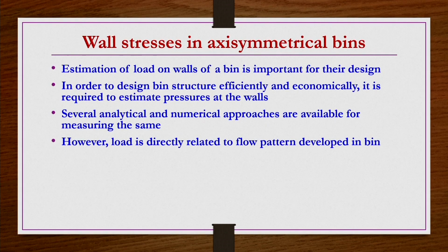However, load is directly proportional to what kind of flow pattern is there inside the silo when the discharge is started, or when the feeder is open to take the material out. So, what kind of flow pattern exists inside the bin is again going to have a very important role on this pressure.